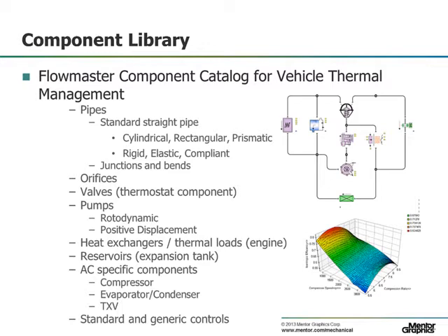Besides the built-in components, Flowmaster also provides a way to create your own component with all the capabilities of a standard Flowmaster component. The interface can generate a code stub as a starting point, and from there you write your code in either C# or VB.NET.